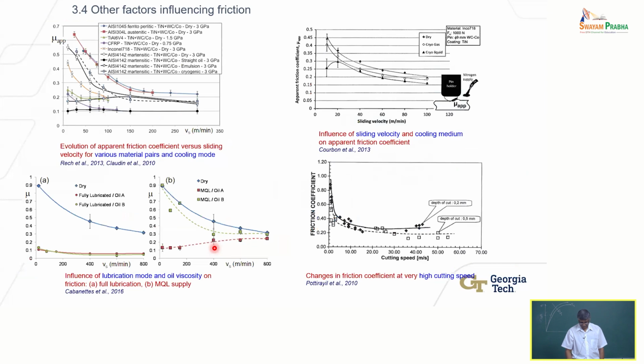Okay, there are many other factors that influence friction, okay? So people have found in machining that, we use coolants. We were talking about coolants, lubricants, etc. even yesterday. So while it is debatable whether the coolant really enters the chip and workpiece interface, I argue it doesn't, okay? But let's say it's still a debated point. But the actual forces do change. So there is an effect, right?